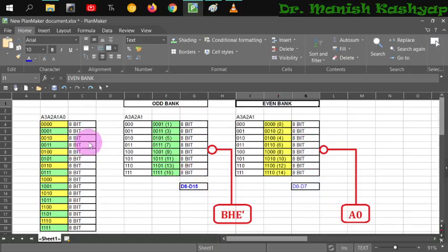right? But if you have only a single memory chip, you cannot connect the entire data bus into the 8 bits of one location, because ultimately out of this memory chip you will have 8 connections coming out to interface the data bus. But then we have got a data bus of 16 bits. So you need additional hardware to interface this kind of memory to your system.